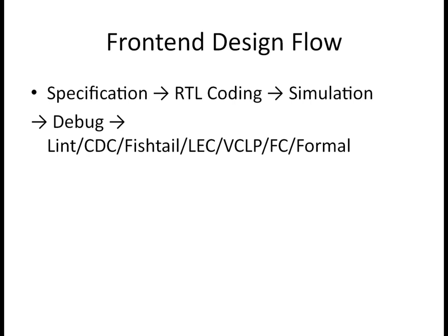Once constraint lint checking is done, we will be doing the RTL verification. That is one of the flows, and there is one more flow in front end called Fishtail RTL constraint promotion. For that, we'll be promoting the IP level constraints to the partition level. Once that is also done, we can make sure the constraints are in sync with the RTL. The next flow will be your LEC.